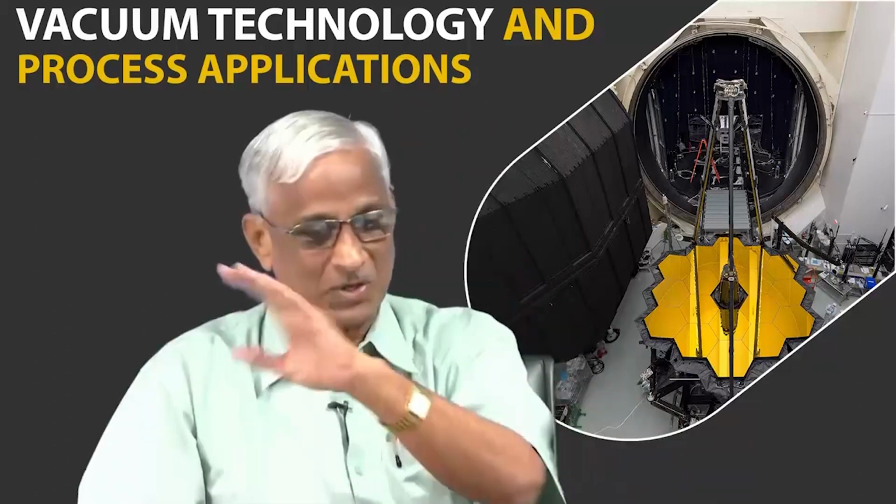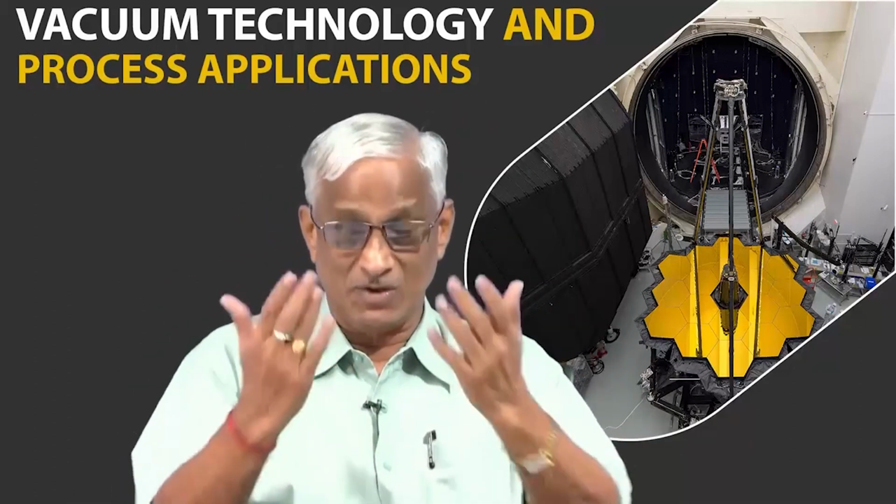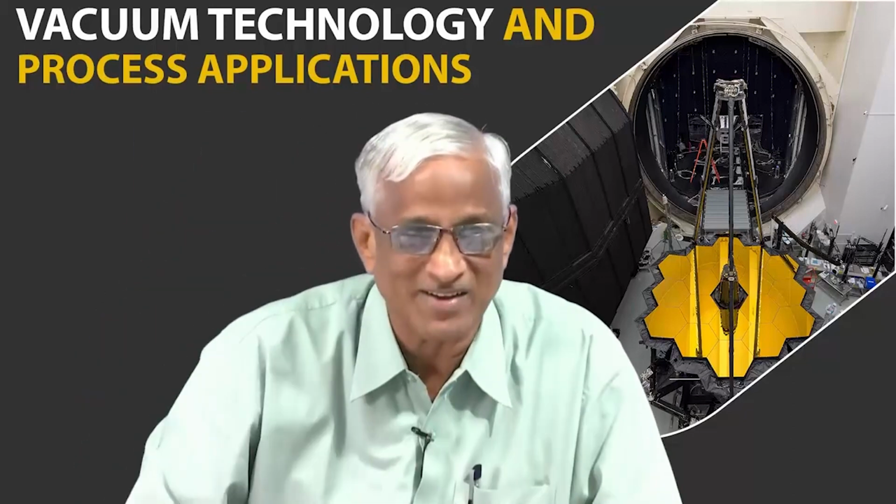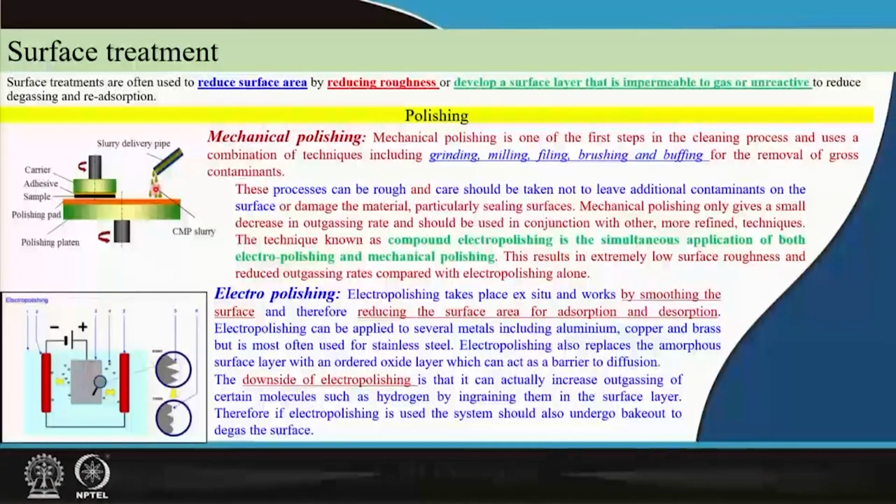It will be shining, because the visible wavelength is of the order of 0.4 micron. If the roughness is less than that, then it will be a good specular reflection. Then you can see your image in the stainless steel sheet, it will look like a mirror. That is why we call it an optical finish. That is the final finish you will get by a combination of mechanical polishing and electro polishing.